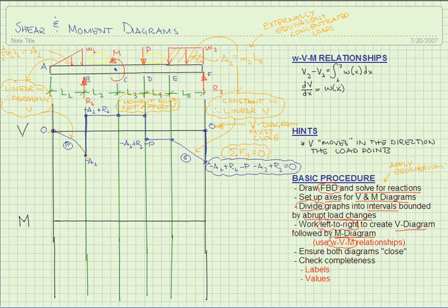And in order to do that, we have similar relationships relating shear to moment from what we used relating load to shear. One of those relationships is that the change in moment between 2 points is equal to the area under the shear curve between those 2 points, and similarly, the slope of the moment diagram is equal to the magnitude of the shear curve. Those are the two key relationships that we will use when building the moment diagram. Now, once again, the moment diagram, just like the shear diagram, must begin at 0, and we're going to need to calculate a lot of different areas.